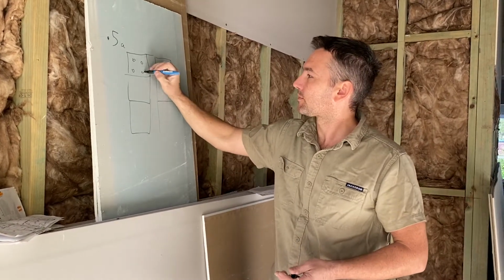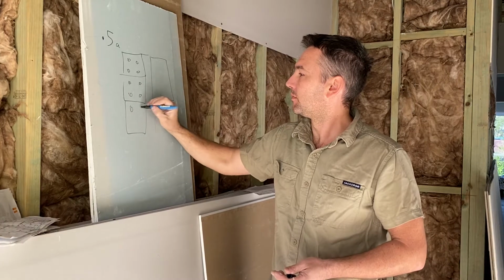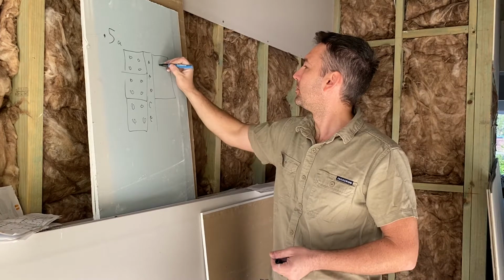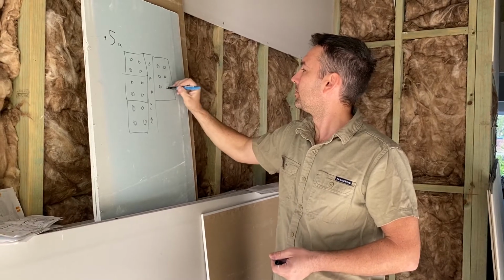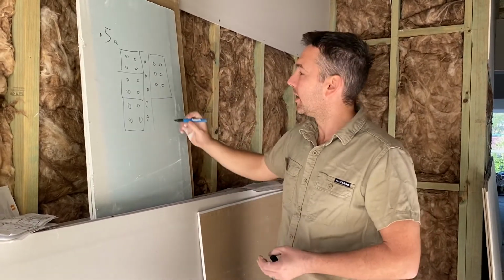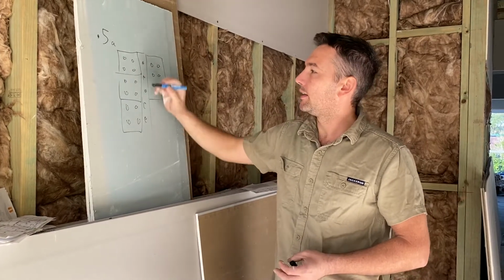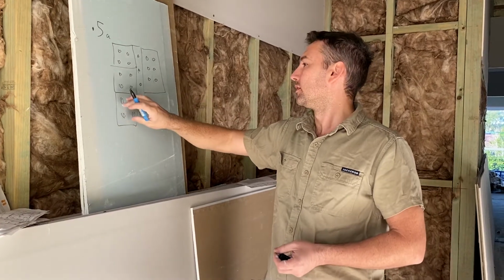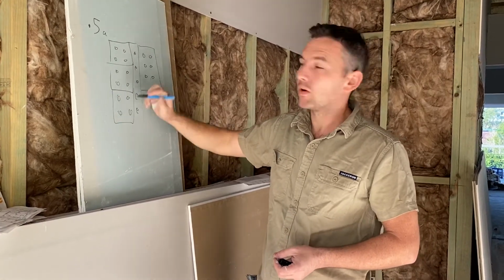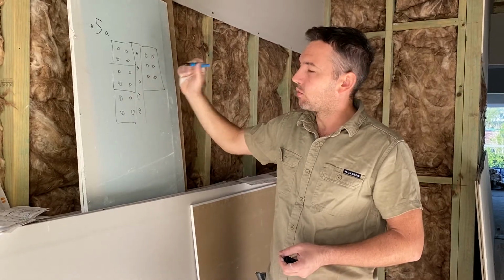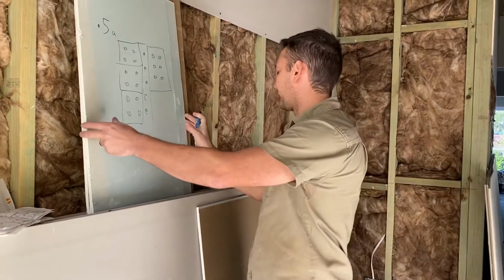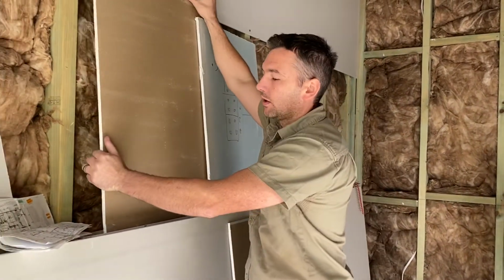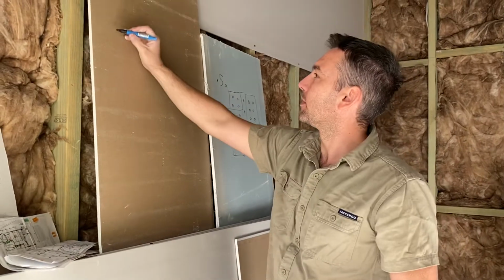And say that's all our downlights inside the house. How to plan that run out is we've got 4, 8, 12, might put all of those on one circuit. And the way that you run your circuit, you actually have a bit of a choice. You can power your light switch, or you can power the first light. I'll give you an example of what I mean here.